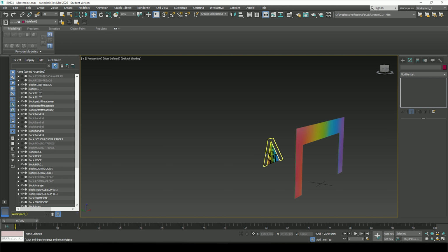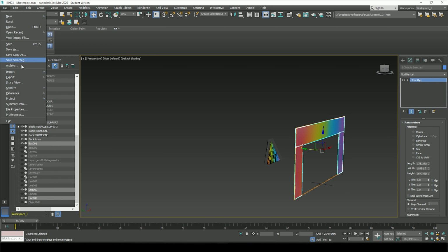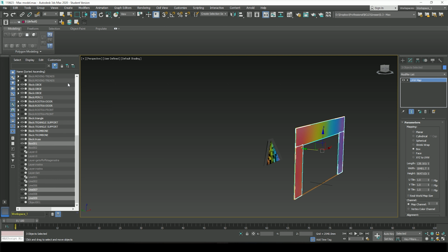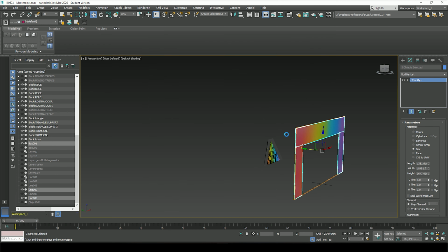So now I'm going to export these as FBX files. Now these are the ones that are going to lose their positional information, so we've got to accept that up front. I'm going to do an FBX export by going export selected. It's gone to my folder. I'm going to go to FBX this time. Now I'm going to name this as Proscenium. Really important you name everything and name them well. Make sure it's consistent across all the other things you name.